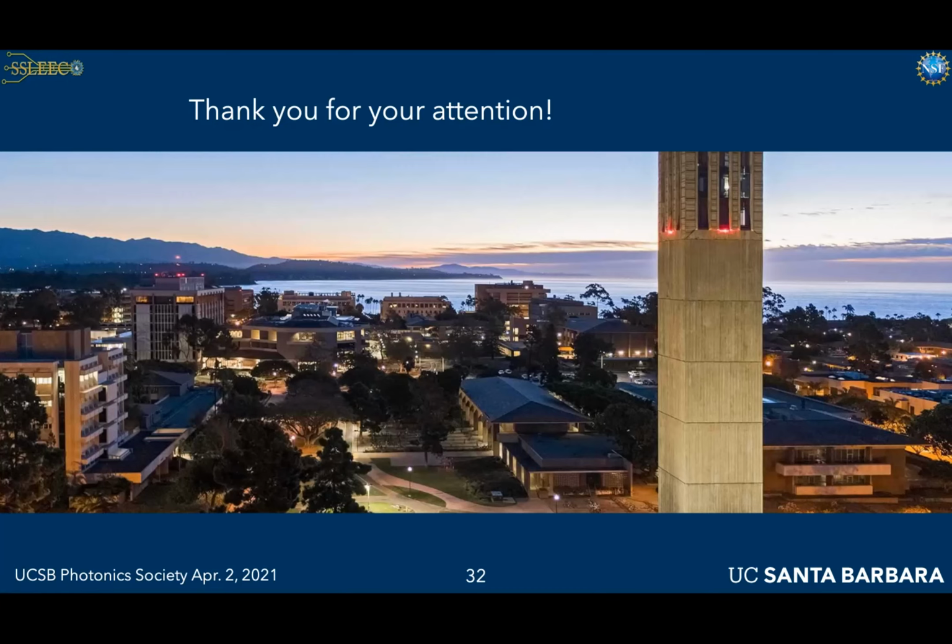Hey, Chris. Thanks for the talk. It's a good talk. I have two questions. So one is, I'm just curious what the composition of your EBL is typically. Yeah, it's usually around 80% aluminum. 80%. Okay, so it's like 30% above what your AlGaN composition is? Yeah. So the N-type layers and the cladding, that's around 65%, and then the quantum wells are around 45%. I see. Okay.